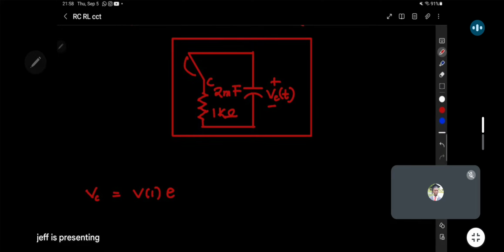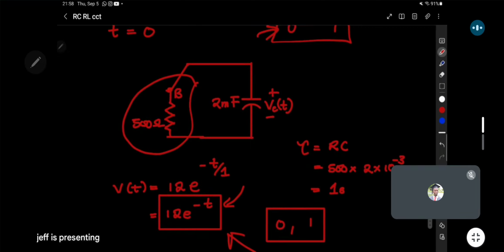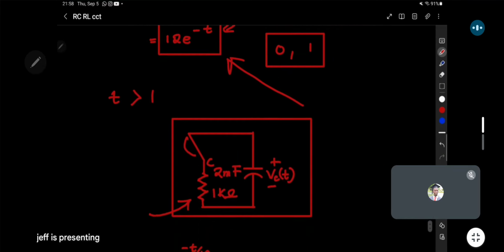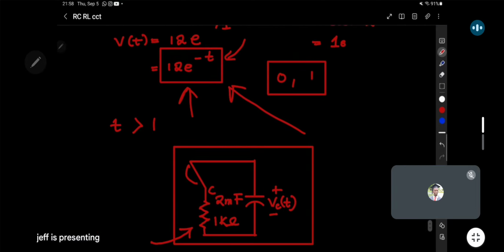We have the exponent there. And from the exponent, of course, you know this is going to be e to the minus t over tau. But what do we have? We've seen that this must be the initial voltage which was present, not V0, the one we started with, but the V0 for this orientation. The 12 volts we had was the V0 for the first, when the switch was moved to B. But when the switch was moved to C, the voltage which was present is going to be governed by that expression.